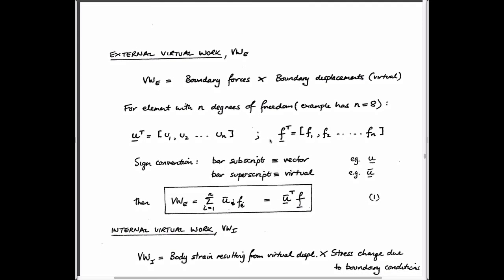And so we said that if you have an external force acting on this body and it goes through some displacement, then that force multiplied by the displacement you apply, the virtual displacement, is equal to the external virtual work. We can calculate that. Likewise, we can calculate the stress that force applies on the system, and the displacement that goes through will generate a strain, and we can calculate that and calculate the internal virtual work. So we'll attempt to calculate both of those.